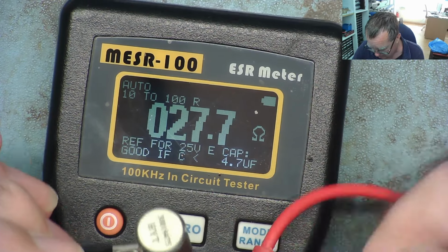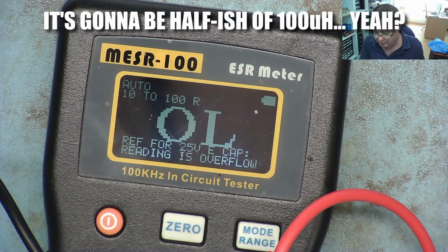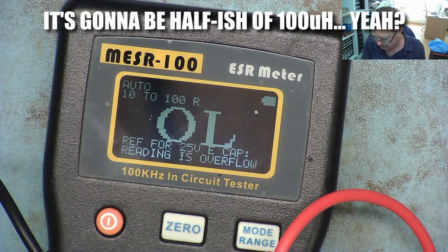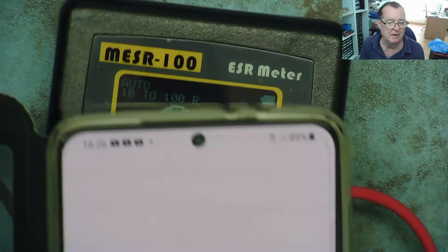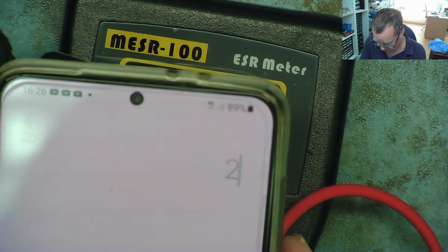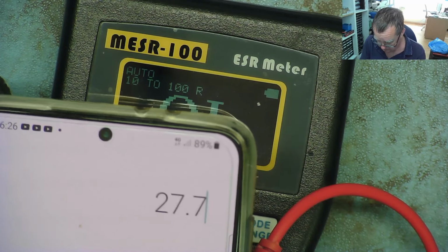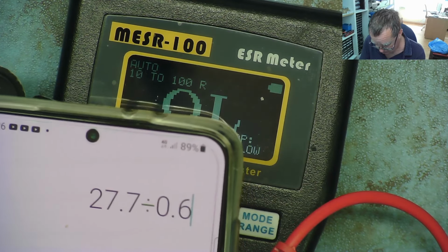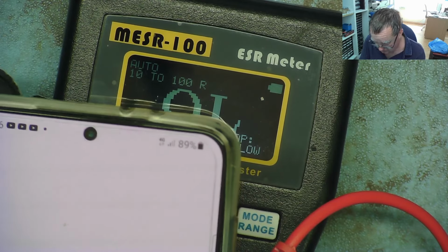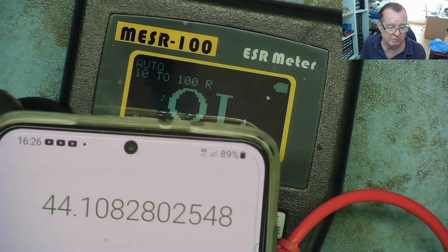27.7. Yeah, it's less than 100 microhenries. You can figure that out. So again, let's do the formula and work it out. Okay, calculator again. So 27.7, that's what we measured in ohms, divided by 0.628, 44 microhenries. It's probably a 45.